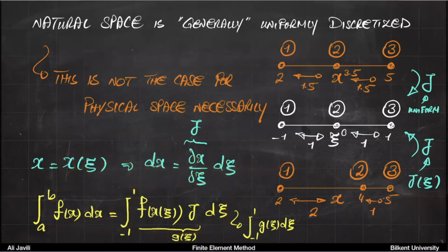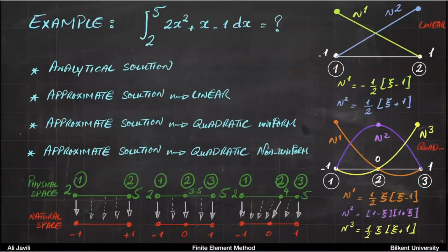Does that make sense? So here you would have maybe a polynomial of order 3, 4, 5, depending on what happens. We'll look into it. But what does that mean for you? That means you should not be fooled by just looking at the order of the integral that you had in the physical space. In this example, again, this is quadratic, but it doesn't mean that you need 2 Gauss points. You need to do the transformation.